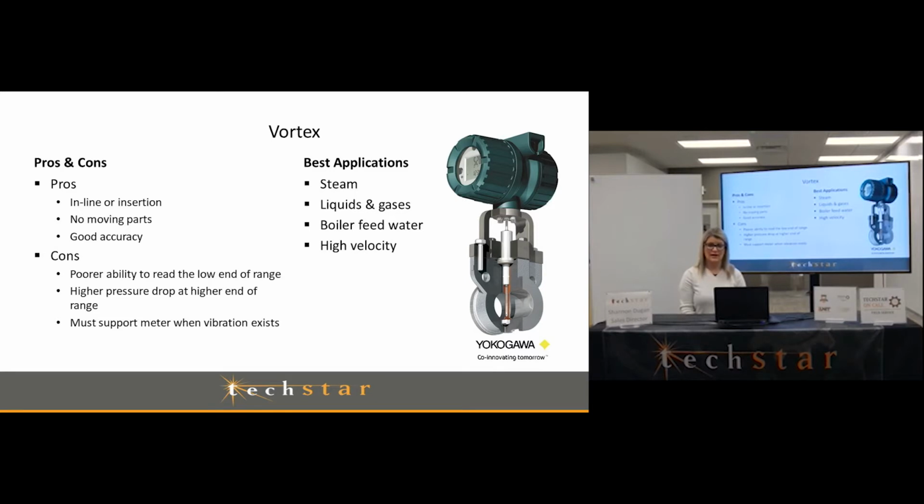They have good accuracy and a pretty good range. They don't do very well down at the low end. So if you need measurement down low flow, just make sure that how low you need it is within the good range of operation whenever you get these sized.